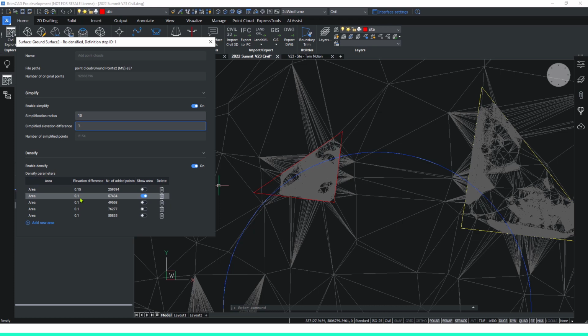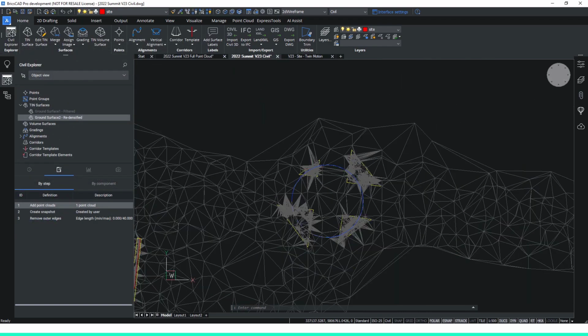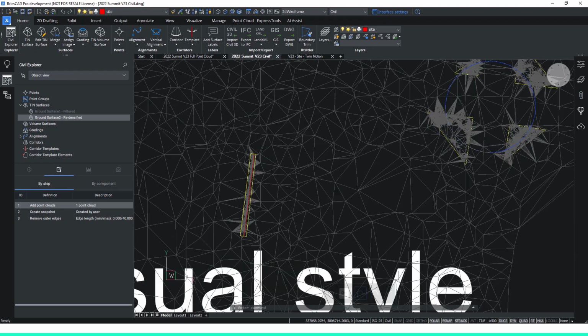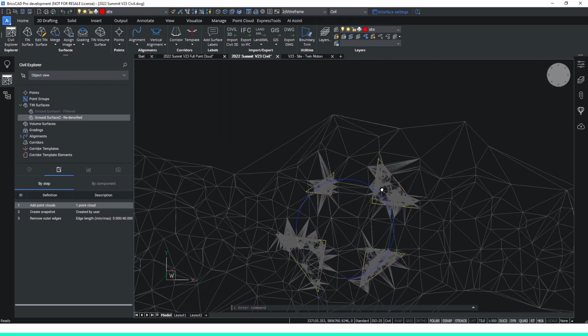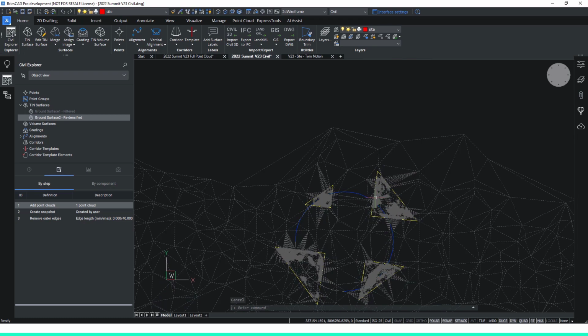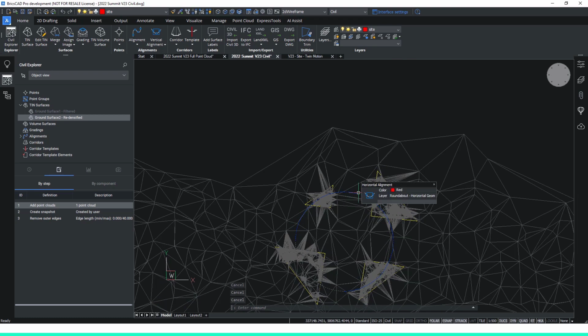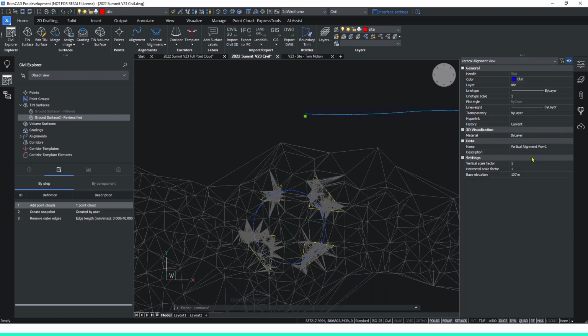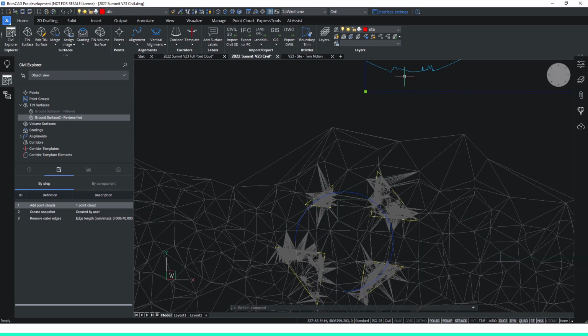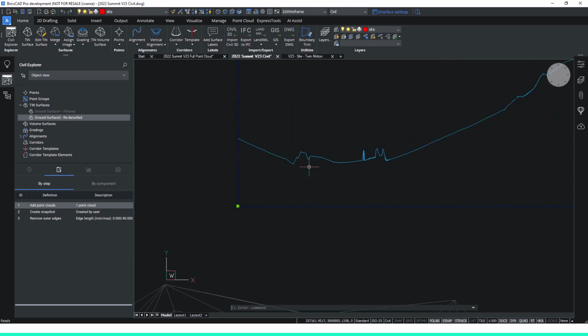We've also added that information to the road widening over here on our left-hand side. So what we can now do is work through these 2 examples that we mentioned. We've got an alignment here for our general roundabout area. If we hover over that, we get the option to create the profile view. We can then select that profile view and change the vertical exaggeration to a factor of 10 to make it more obvious how the traffic islands have been added. So let's type in 10 here in the properties, and we can visually see straight away that the traffic island is very, very obvious in terms of how it's been added.